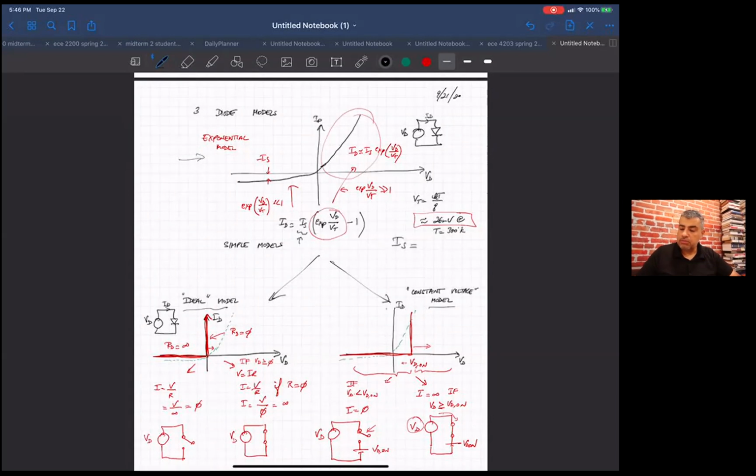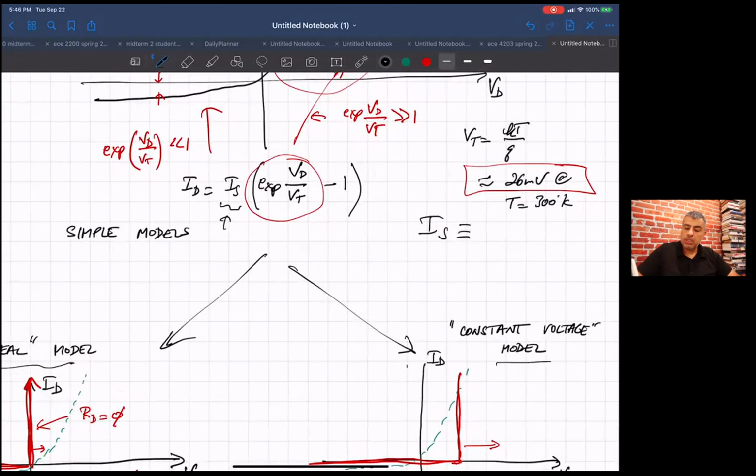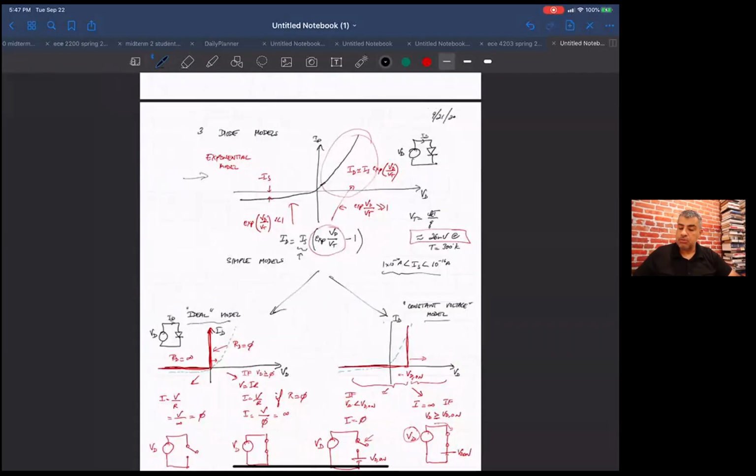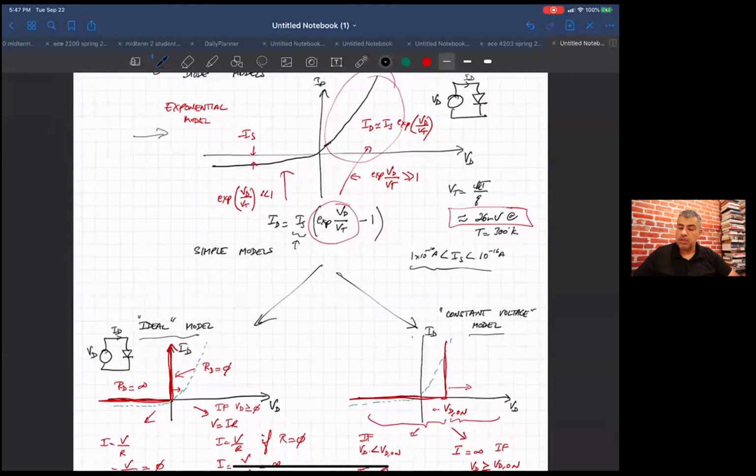And it's a given thing. I don't know if it's called reverse bias current, but let's call it that. Remember, this would be given to you either in the problem, or in a spec sheet if you're really using a diode to design with. It's a pretty small number in terms of amps, but it makes a big difference in the voltage versus current characteristics, because of this exponential behavior.